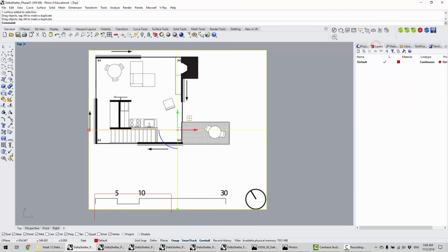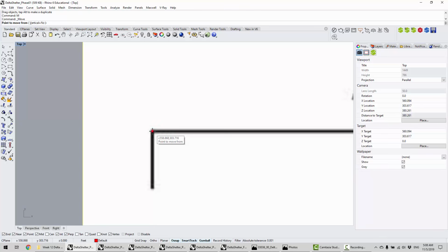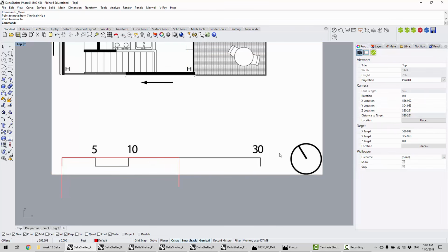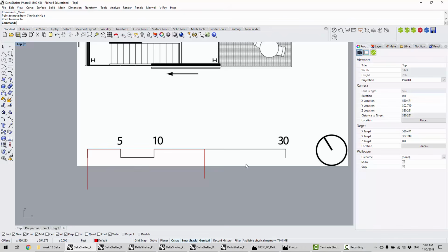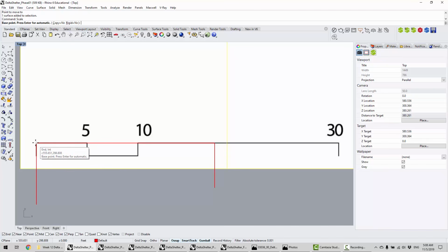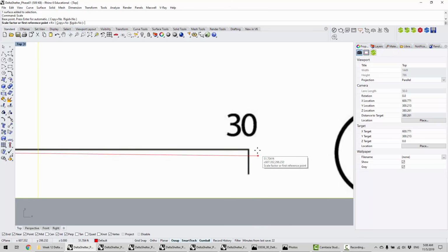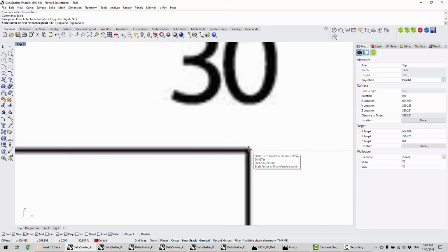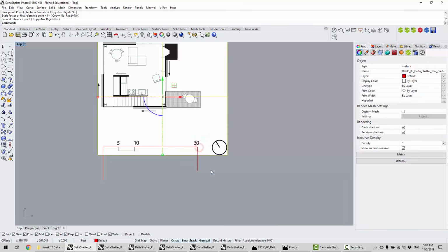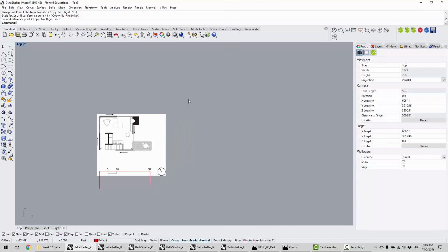Eventually you should assign these to their own layer, and you can do something like this by zooming in, clicking on that point and snapping it to this corner. And now we know, okay, this image has to shrink down, right? This is the 30 feet actual distance. So we'll scale using this as the base point, going all the way down. Make sure your ortho or your smart track is on like this, so it snaps to the right locations. Do that, click here, and shrink it down, match it to this point. So we know that this scale is correct, right?